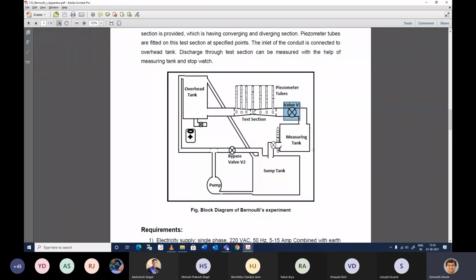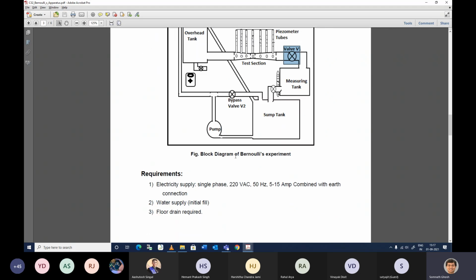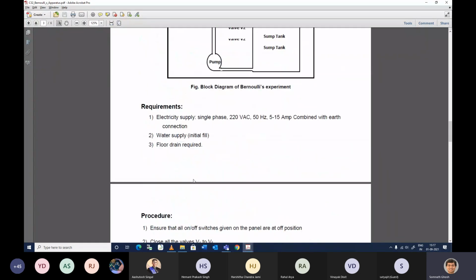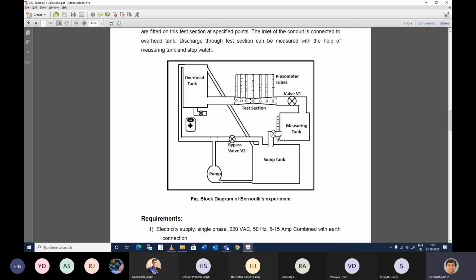Now here you will measure with a stopwatch how much volume of water is releasing at steady state when everything is on. And also you need to measure the time using a stopwatch, that at certain intervals, for 10 seconds or 15 seconds, you accumulate a certain amount of fluid. Now in that entire experimental duration, you always need to ensure point number 9. Just think why you need to have an overflow from this tank to this tank. Just try to think about that.